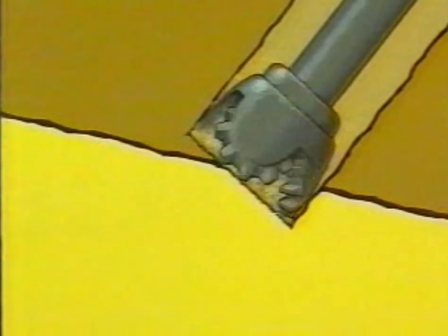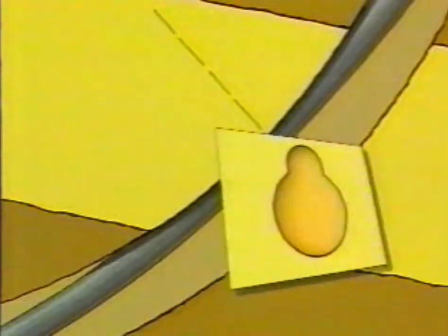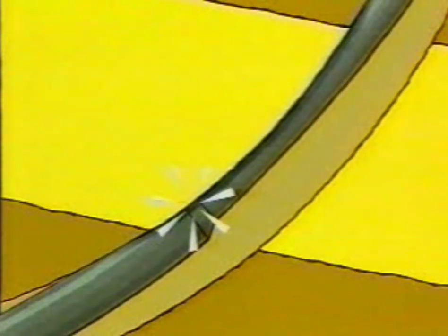When drilling deviated or curved holes, the drill string tends to be forced against the borehole wall. Continuous pipe rotation starts to cut a groove, or key seat, especially in softer rocks. Further rotation will result in a mature key seat, a cross-section of which looks like this. When tripping out, drill collars or stabilizers can easily become jammed, especially where transitions between hard and soft rock combine with severe doglegs. Let's look at that again.